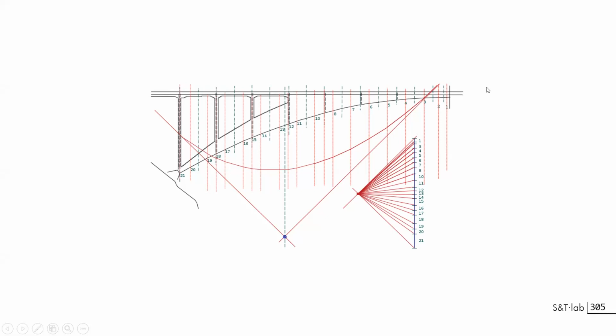So you're just drawing this horizontal line, getting the intersection with the line of action of the vertical force. And you know that the third line has to pass through the hinge and through this point. So you know this direction and you are able to calculate the forces on the support. But you also have the direction of the first ray, the tangent to the funicular polygon, that will explain what the thrust line is all along the arch.